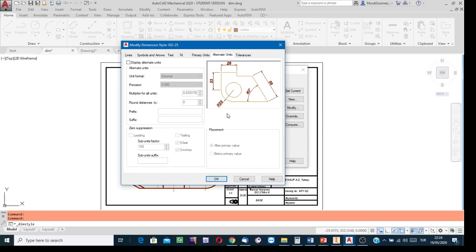Okay, to be able to show the dimensions in millimeter and also in inch, select this box, and thereafter you can have the dimensions in millimeter and also in inch. But here, say that there is no such technician in the company in this scenario, so no need to show the same dimension with 2 different units, millimeter and inch.